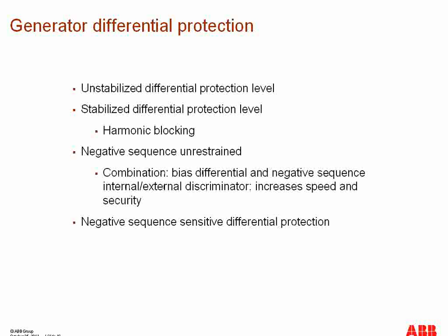There are four sub-functions of differential protection. The first one is the unstabilized differential protection level. For very, very high stator faults, we will use this unstabilized differential protection level, and the protection will give out the trip signal without any regard to the stabilizing quantity.